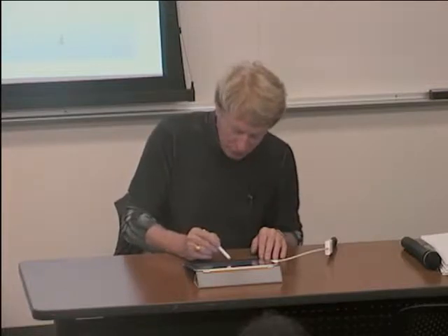Okay? For VIH, the same thing, but now for opposite operational modes. In this case, the NMOS has to be in resistive mode and the PMOS in saturation. Now, this is fairly complex. I can promise you that when you start writing down the equations of a transistor, you will get a very long expression. Long expressions are kind of cool. They fill a lot of paper, but it's very hard to understand what the trends are.